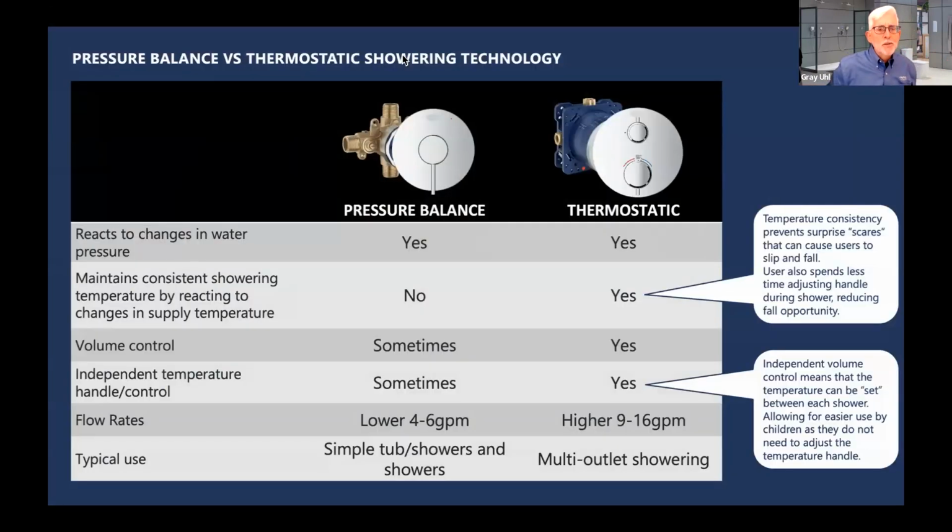The difference between pressure balance and thermostatic, reacts to change in pressure? Yes, both of them do. Reacts to a change in the temperature of the water? No, the pressure balance does not, but the thermostatic does. Volume control, typically you do have volume control on the thermostatic, you don't on the pressure balance, but we talked about that. Independent temperature, sometimes on the pressure balance, but always on the thermostatic. You always got that big knob just for temperature.